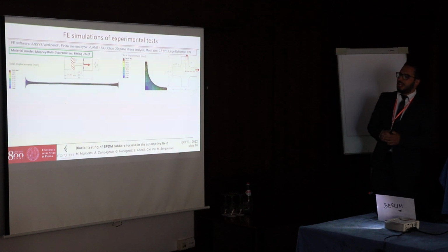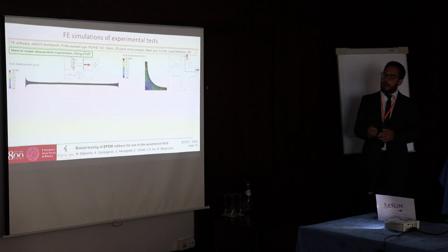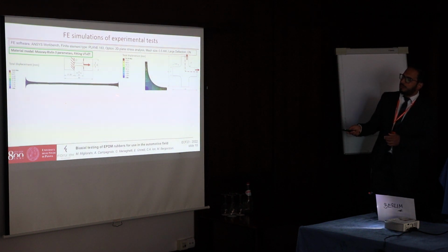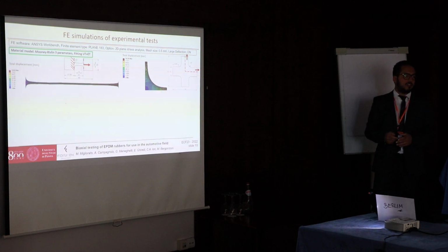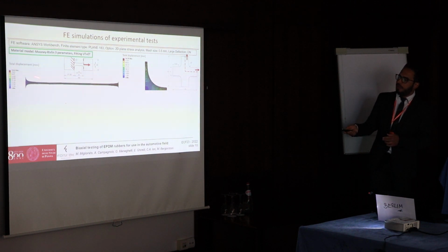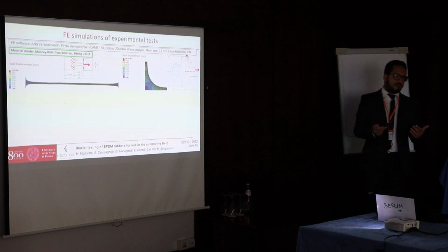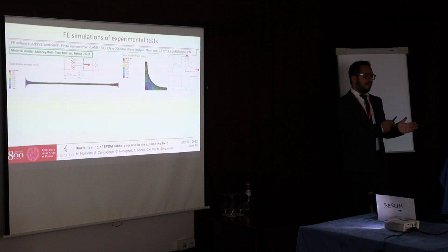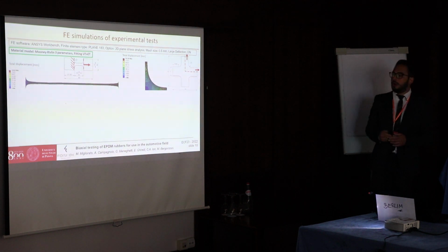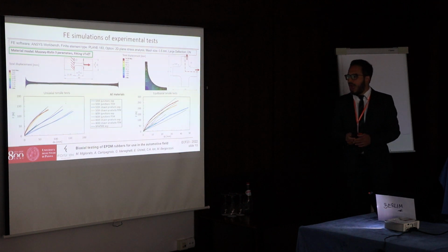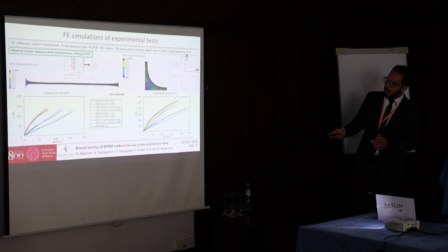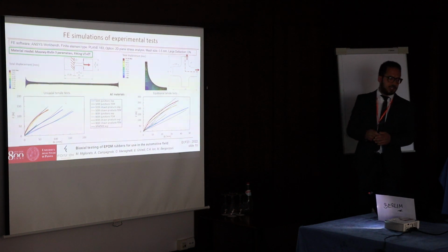We have performed a finite element simulation of the uniaxial test and also the equibiaxial one by applying the experimental displacement at failure at one end of a specimen and by calculating the constraint reaction at the opposite end of the specimen. So we have in hand the displacement at failure and also the load applied to the specimen. Therefore, we have derived the simulated load-displacement curves for both uniaxial and equibiaxial tensile tests.